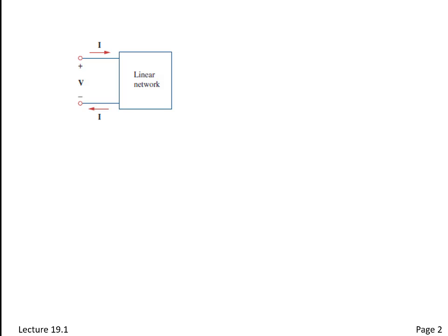And often there is a source somewhere out here, attached here. So we apply a voltage and a current is forced in. Or we apply a current source and a voltage appears across the network. We call this item right here a port. So a port, and we need this because we're going to be talking about two-port networks. So a port is two pins, two terminals